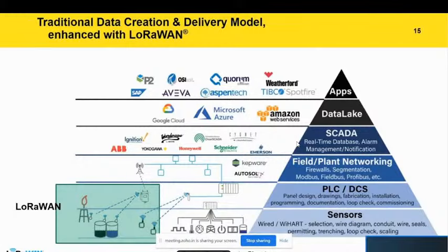We can make some of the sensors wireless, like some of the remote sensors, or some of the sensors that are not utilized by the process control but still we need data, and they were not planned earlier in the commissioning of the plant. We can place these sensors using a LoRaWAN network.